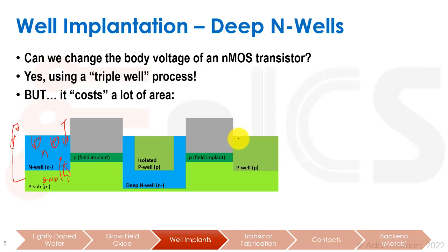And over here we have the same thing with a PMOS. So we're going to put an N+ and an N+ over here. We get our transistor. We're going to put a P plus over here and connect this to ground, and that's fine. There's an ohmic connection over here. Remember, this is already at ground because we have these well taps, for example, over here. And so everything is okay over here, and this is isolated.